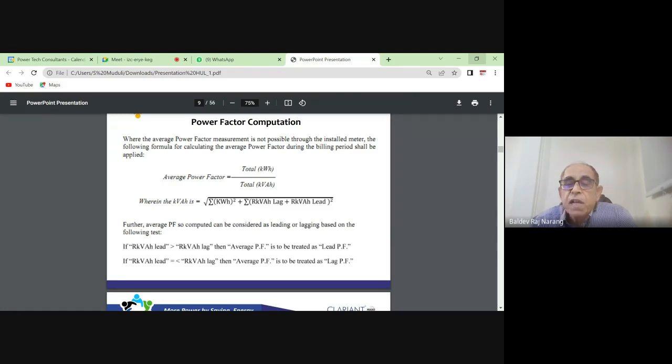So in India, we started with these power factor incentives. Then everybody started maintaining power factor aiming at unity, but they were actually maintaining more than unity. Then they realized that again there is a problem, because suppose they require 1000 kVAr and the actual connected capacitors are maybe 3000 or even 5000. It was happening that way. So again it is leading to over voltages in the grid and even at the consumer end. That way, the requirement comes for shunt reactors. You have an inductive power requirement when you are overcompensating.